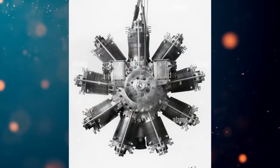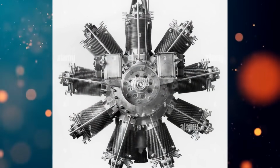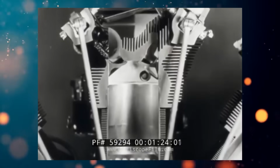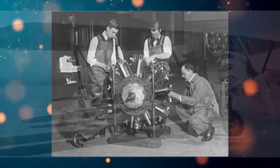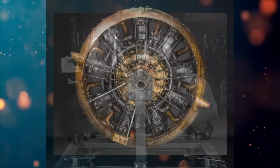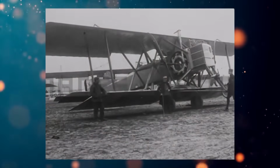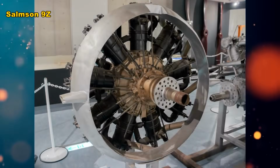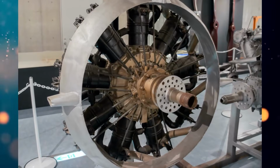Star-shaped stationary engines, from the beginning of their history in 1901 up to 1919, remained in the shadow of their relative. Such early designs suffered from overheating except for the very rare engines with liquid cooling. Early aviation was slow, and natural airflow was not enough for such an engine. Most radial engines had air cooling, but one of the most successful early radial engines and the earliest stationary design created for World War I combat aircraft was the series of 9-cylinder water-cooled radial engines, Salmson 9Z, which were produced in large numbers.